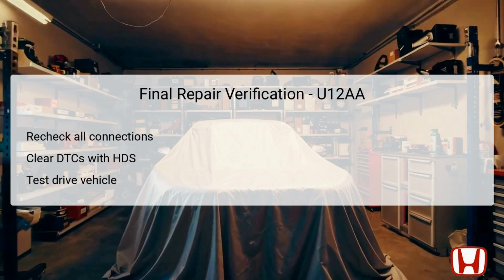The final repair verification step is crucial to ensure that all repairs have been effectively implemented. Start by rechecking all connections made during troubleshooting to ensure they are secure and properly connected. Once satisfied with the connections, use the Honda Diagnostic System, HDS, to clear any DTCs present in the system. This action resets the modules and prepares them for new testing.